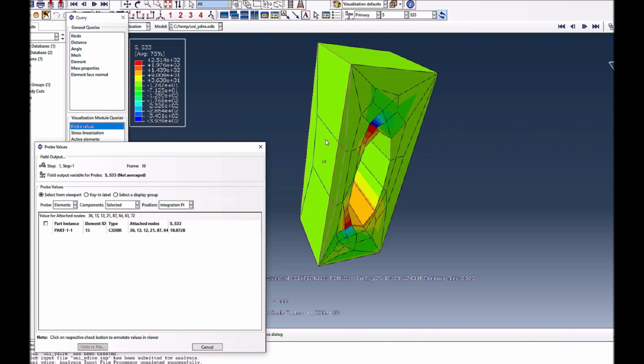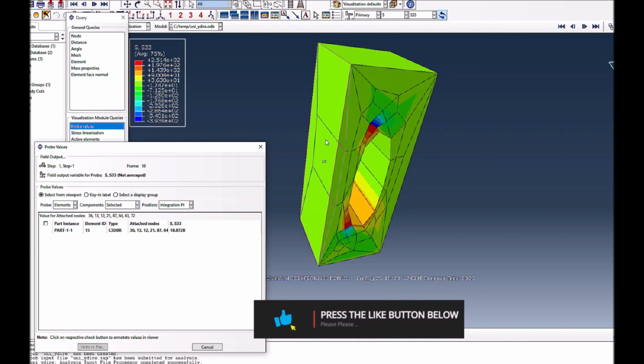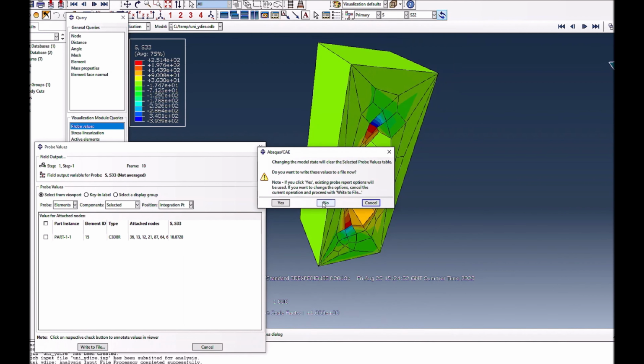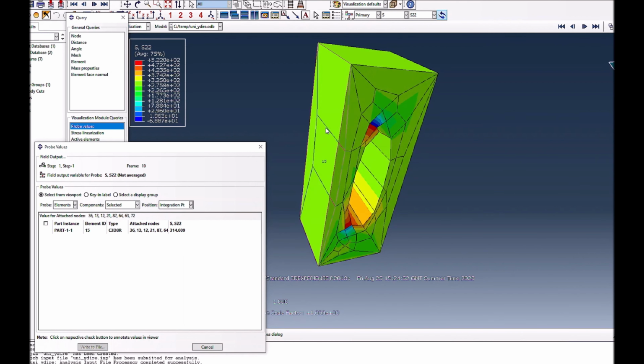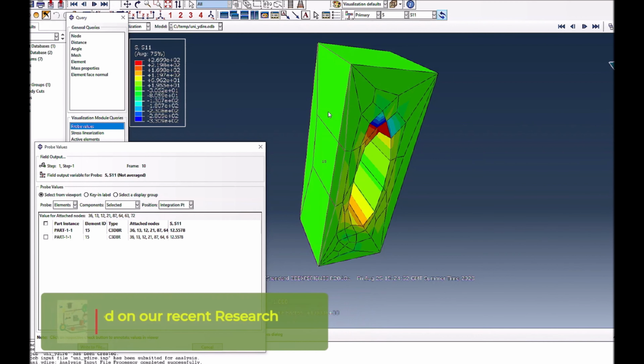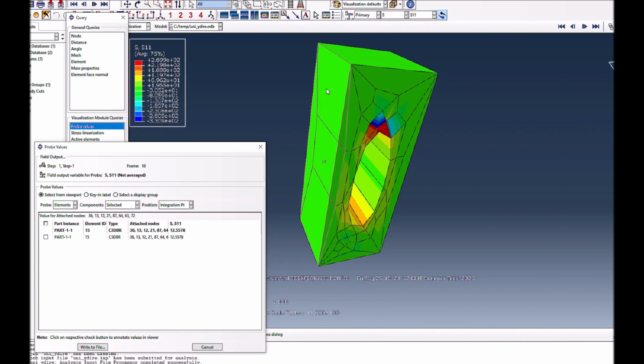So you see the stresses are still low, which is around 18 as compared to the others, but they are not zero. Similarly S22, that's also very high. That should be high because you're pulling in that direction. And if you go to S11, then they should also be small, which is around 12. So they are small, but they're not zero because you still have the effect of these stress concentrations.